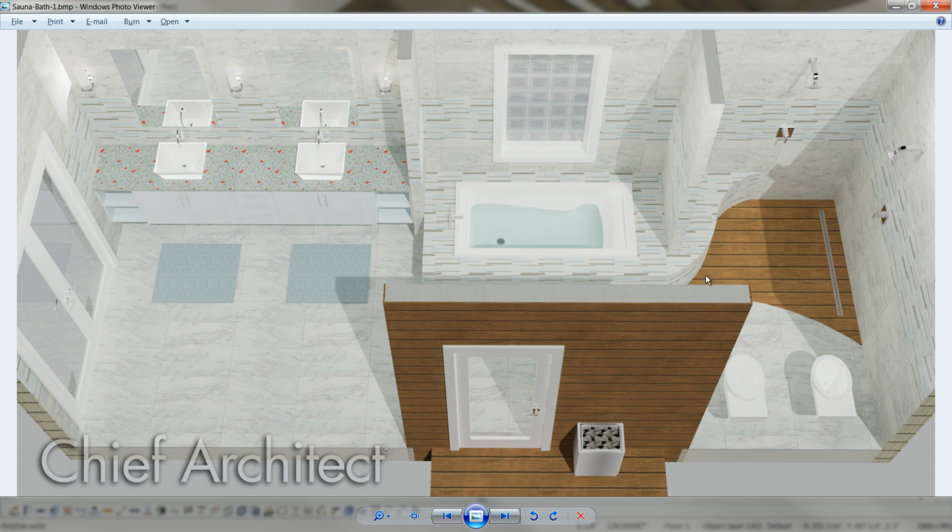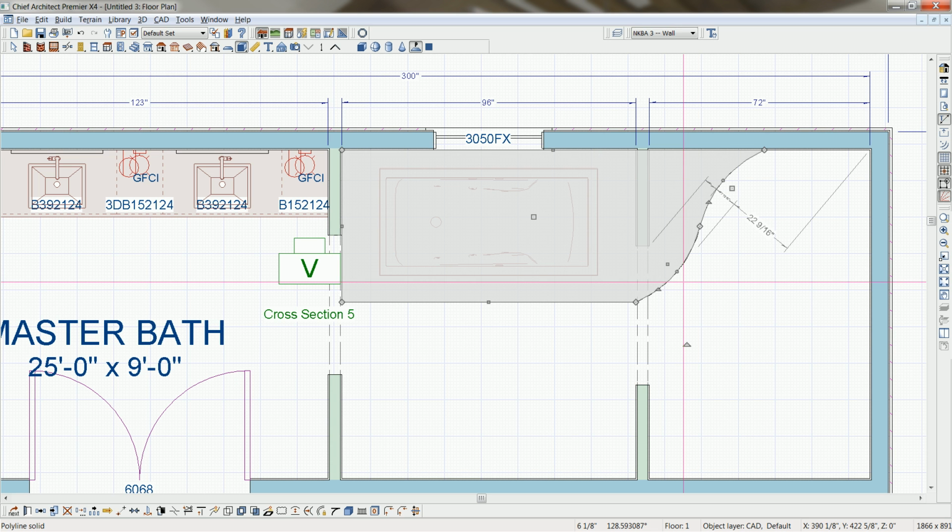The next thing I want to do is have the flooring for the shower exactly match the tub platform. I could do it a simple way where the material just goes underneath the tub platform, but if I do this exact, the materials list that I generate for all the materials needed will be more precise. It's actually just about as easy to do it the right way.